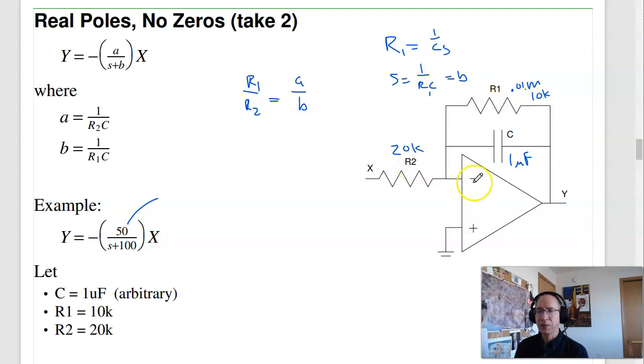That's the second filter. The nice thing about this one is the gain can be bigger than 1 or less than 1. The RC filter, the DC gain is always 1. The other nice thing is I can cascade a whole bunch of these. I don't have to keep on making R get 10 times bigger. The input impedance of the op-amp is infinity, ideally. Output impedance is low. I can cascade these and not have any loading issues. But it takes an op-amp to implement each stage.